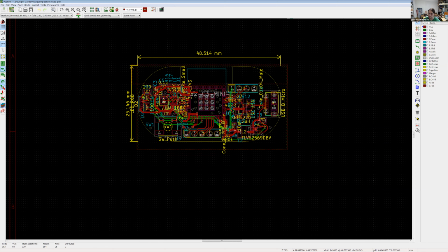Then you take that panel, you run it through an oven. The oven has a temperature ramping profile, so it'll ramp the temperature up at a slow rate, and then it will reflow or melt all the solder on the board, and then it will go through a cooling period and cool off the board. And then what I'll get at the end of that is a panel with 10 boards, and if I design the panel correctly, I'll be able to do programming in that panel directly.